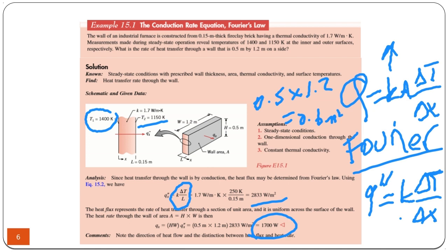Normally, you have a small boiler at your house for radiators, about 20,000 kilocalories per hour. This is enough for a 100 or 150 square meter house. But most of the time, you use only one third of this because it doesn't operate permanently, right?